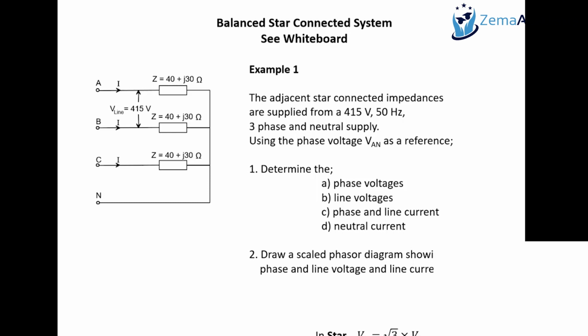So we are going to use the famous equation V equals I times Z. But whenever you use Ohm's law, you are calculating the phase currents, for example. In the star connection, the phase currents and line currents are equal, but in the delta connection, it is the other way around. So whenever we use Ohm's law, we are using the phase values. Remember this point.